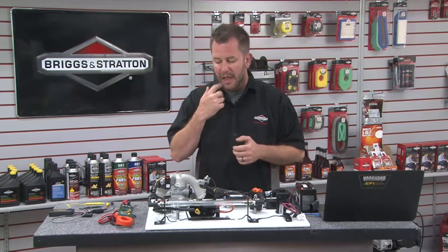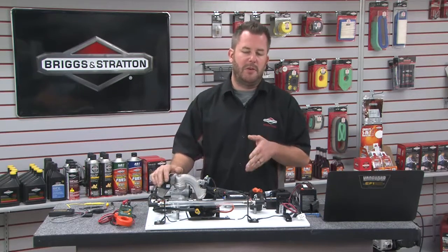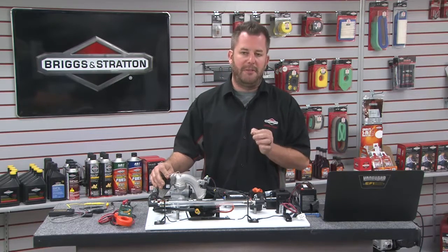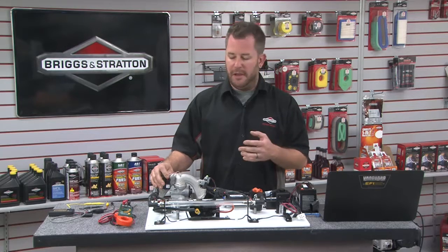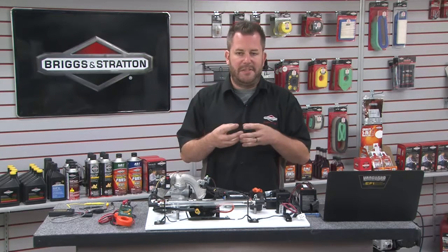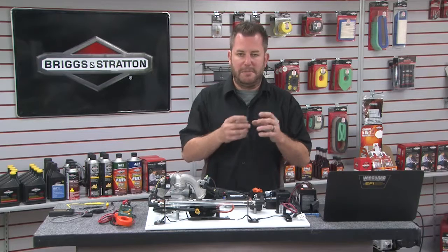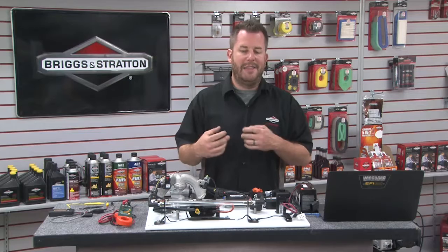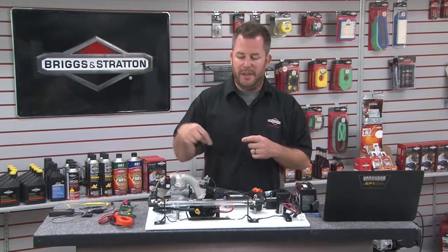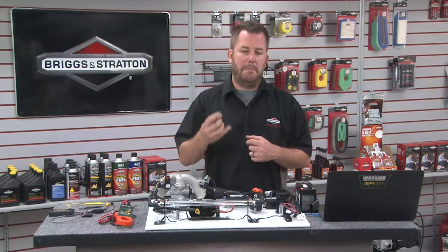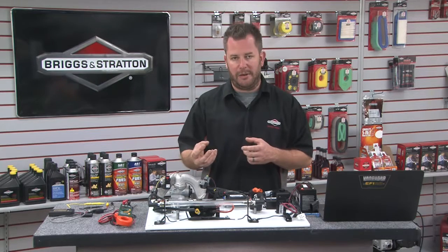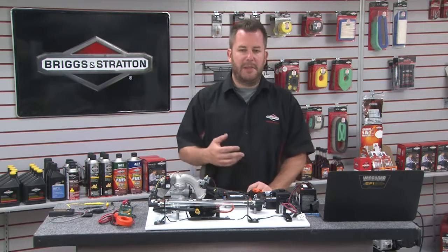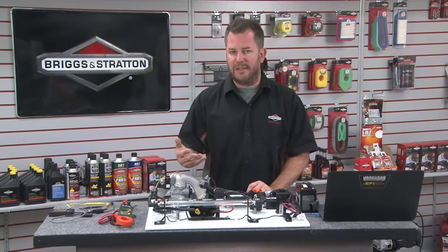So let's begin. Now, the manifold air temperature sensor, if you remember back a couple of sessions ago where we talked about the manifold air pressure sensor, or MAP sensor. Now, it's a sensor that is a combination piece here. There is the MAP part of it, which monitors manifold vacuum. And then there's also a thermistor built in that drops down into the intake runner that measures the incoming intake air temperature. Now, the reason why we need to measure that is because that's really our gauge on air density.